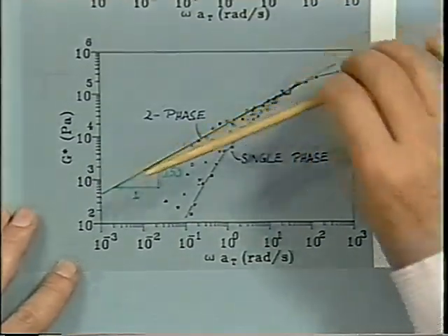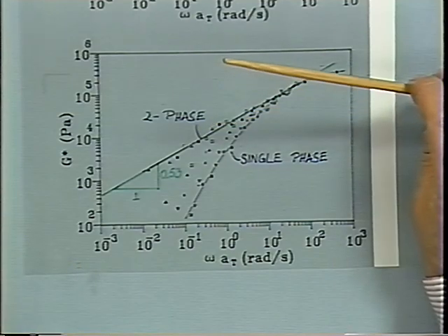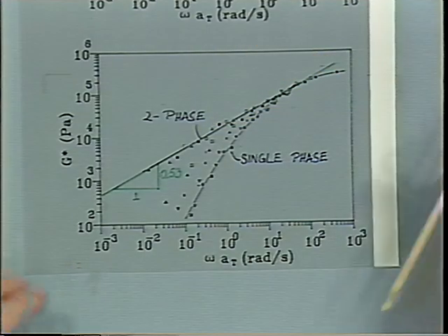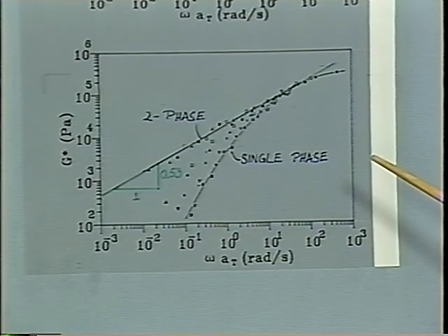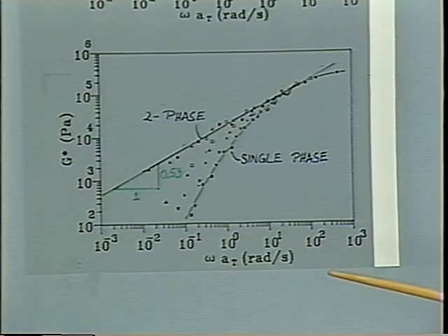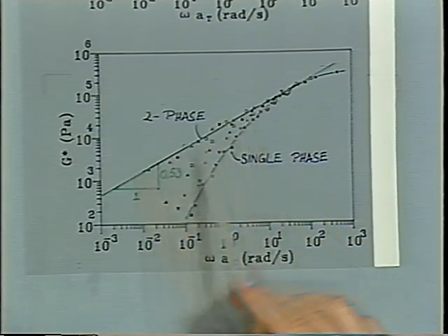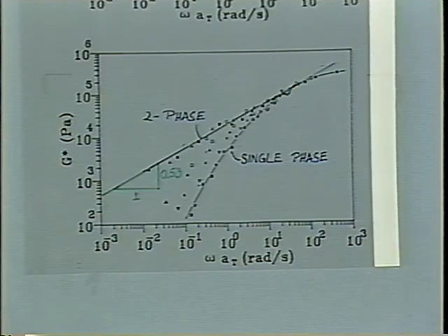We were interested in power law spectra in connection with gels, the gel transition. So the formation of the order is reducing molecular mobility. So we are producing a network by ordering the material. So in that sense, it's also a solidification process and has a very similar fingerprint as the sol-gel transition in liquids. Now, this was already in '78. So it has been found in many, many laboratories, a very established fact.